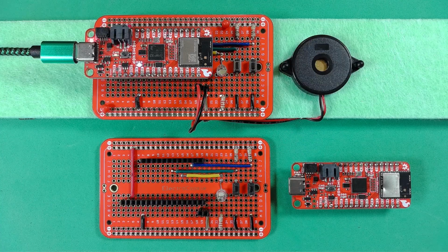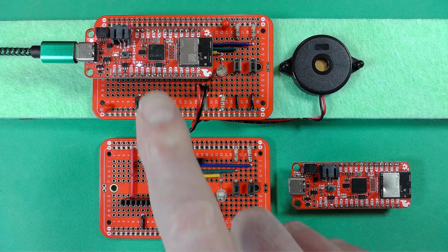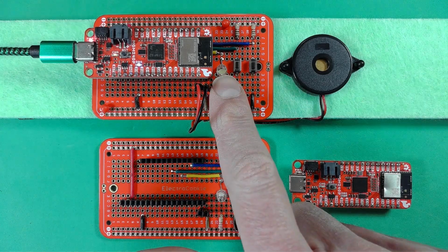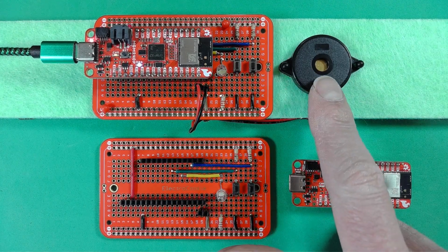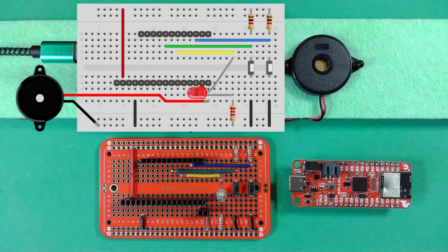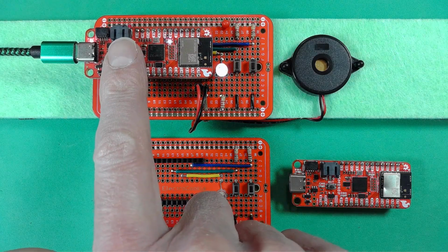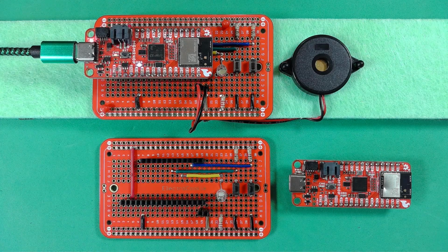The final board that is compatible, but requires more work, is the SparkFun MGM240p Thing Plus. This board only has a single LED and no buttons, so you'll need to add a second LED and 2 buttons in addition to the piezo buzzer. You'll find the breadboard wiring for this in the GitHub repository that accompanies this devlab, and the prototype board setup I will use in this video follows the exact same wiring. This board also has a connector for a rechargeable battery. There are links to further information on all these boards in the video description.